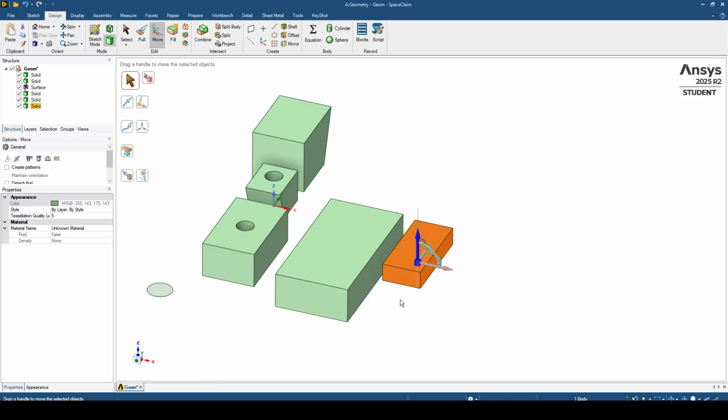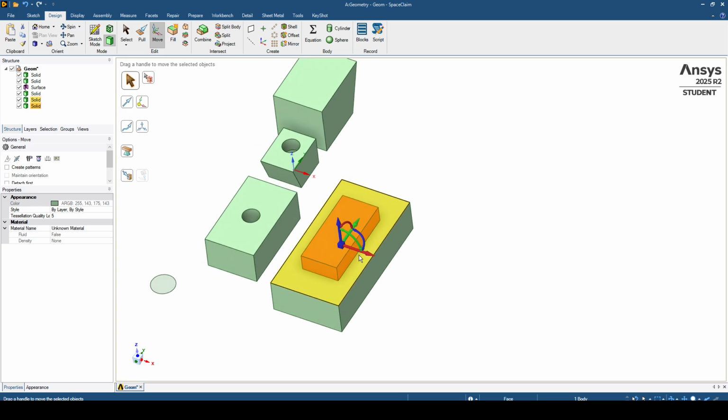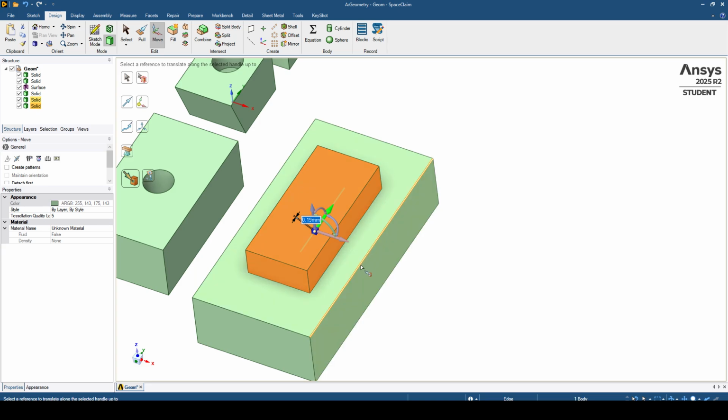We have multiple ways. Right now it's just a tutorial about how to use a combine feature, so I can make it arbitrary. We can select this coordinate system and put it at this location, or even move it along these directions. Or if you want to put it on the middle of this rectangle, we click on this direction, again click on up to, and as you can see, if you move your mouse and through the snapping tool, we will reach this middle point.